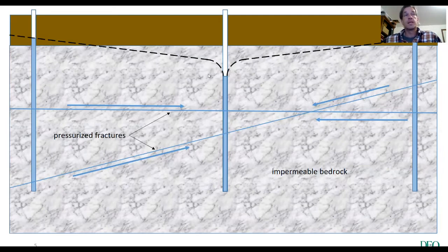And these types of tests are very diagnostic for describing important components of the system that you can then use to forward model or predict how an aquifer might respond to pumping at different rates or for longer periods of time, or if you put in an additional well, what that might do to the system, and can help you answer practical questions like that.